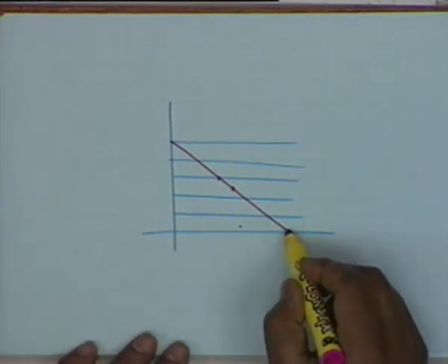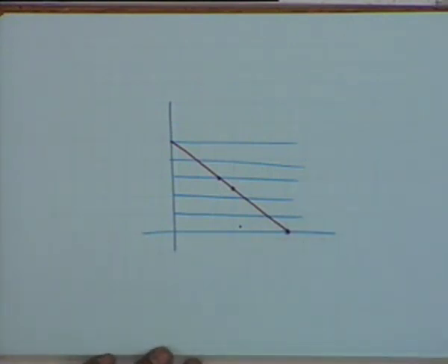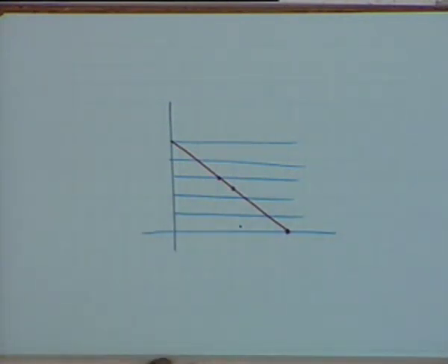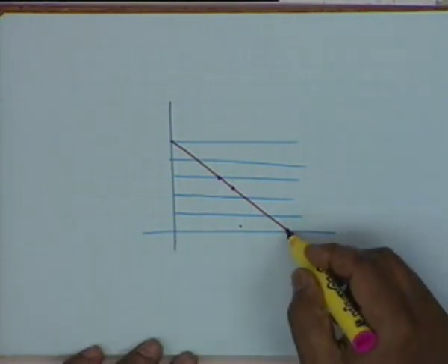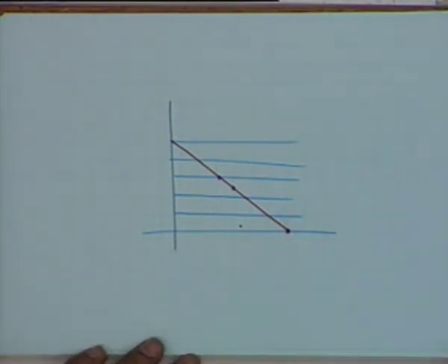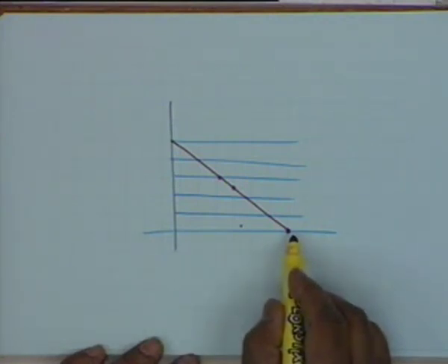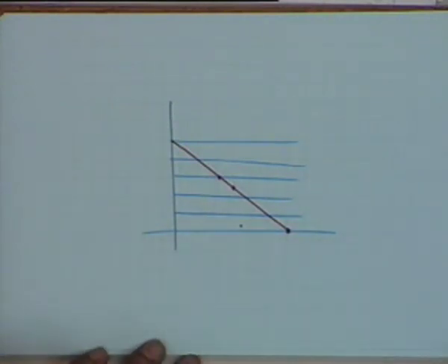But suppose Q point is here, then obviously it is only the positive half cycles of the base current which will cause a collector current to flow. For the negative half cycle the collector current shall not flow, because I sub B cannot go negative, all right. This is the maximum, the current is not injected, and therefore the collector current has no obligation to flow, the collector current shall not flow.